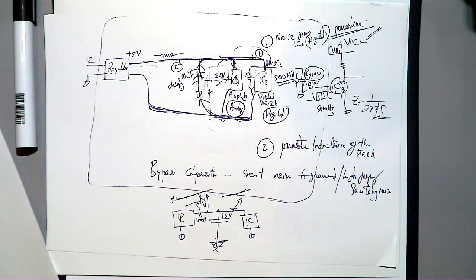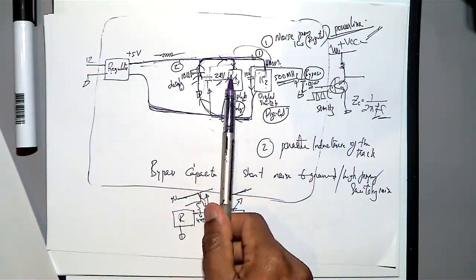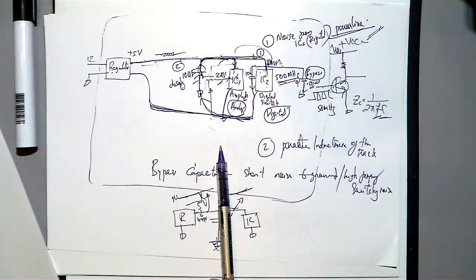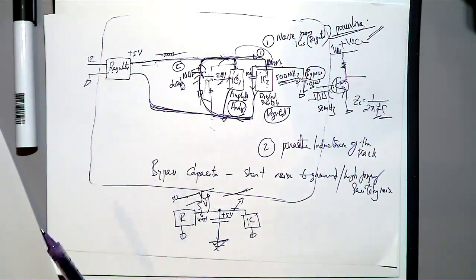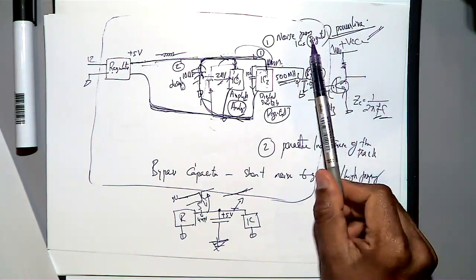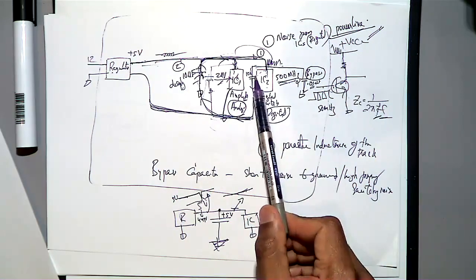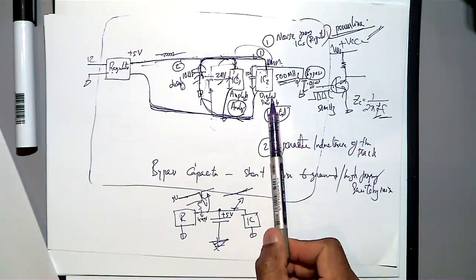So that is important. Then the problem is, you got a decoupling here that is applicable to only a couple of ICs. Then again you need to connect another decoupling. You know what I mean? Still you need a couple of decouplings. So then we solved two issues. One is the noise from the power line. So these are the power lines we bypassed using these bypass capacitors.